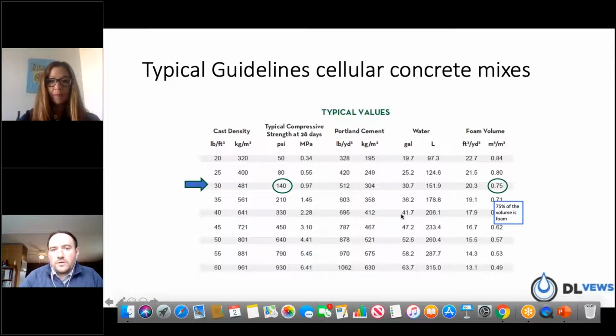So I often encourage folks to lighten the density, the wet density of the mix, because as they'll find during their design, unless there's some extreme live and dead load on that pipe, even the lower strength or lower density grouts will suffice, and then also have a factor of safety built into it. Oftentimes they're shooting for 500 PSI, 1000 PSI, and those are really flowable fill type strengths and then some. Whereas on the average, we'd be somewhere between 100 and 300 PSI, typically speaking. And most of the time that's sufficient. But it should be checked always.